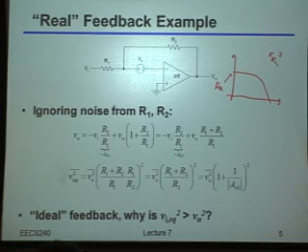If you remember, the reason we said this happened was that we weren't feeding the input directly into the amplifier itself, but rather passing it through this resistive network first. In particular, what we were really doing was attenuating the input signal before we fed it into the amplifier itself. Because of that, that's really why the noise got worse.